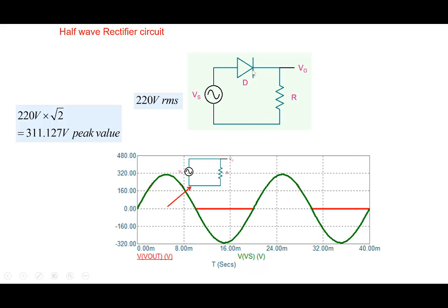The diode drop may be 0.7, 0.8 or so. So as a simple model, we have neglected that, assuming the diode to be like a short here. And so in the positive cycle, this is how the circuit is, and that's why V0 is almost equal to Vs, which is what we see here. There is a drop across the diode, but we are not able to see it because it's small compared to the value of the voltage that we have here.